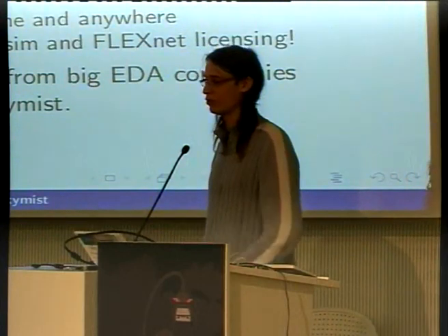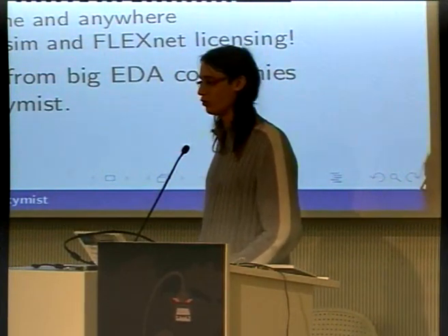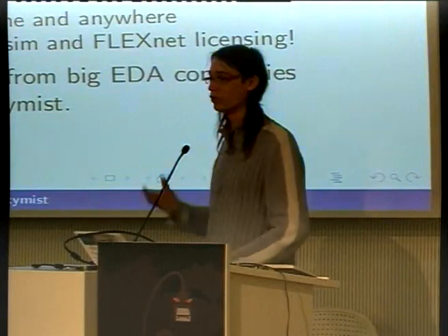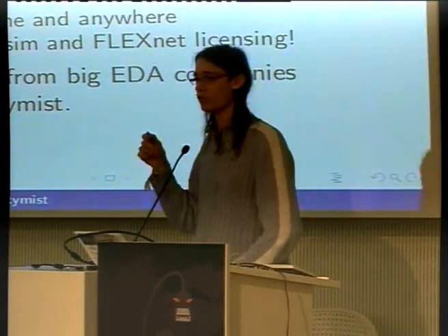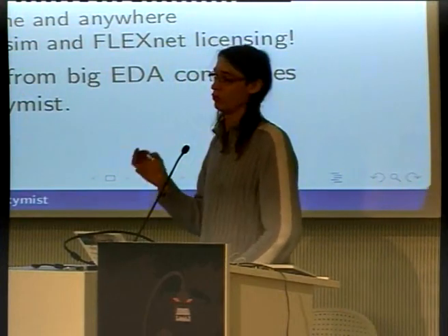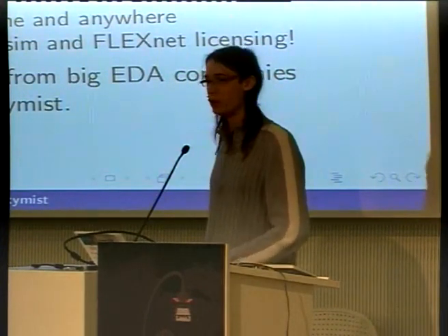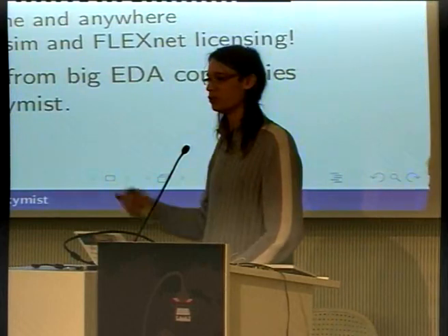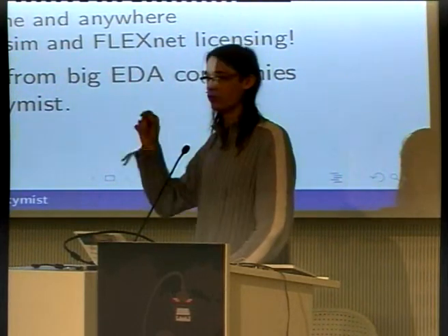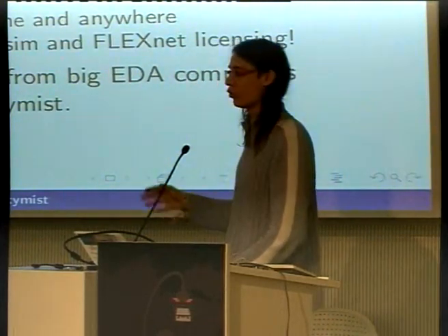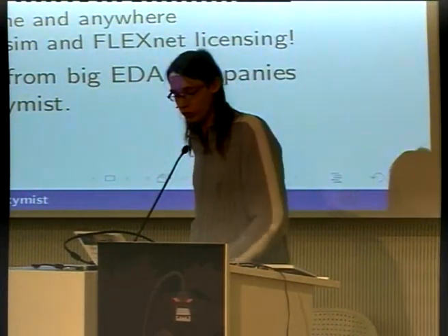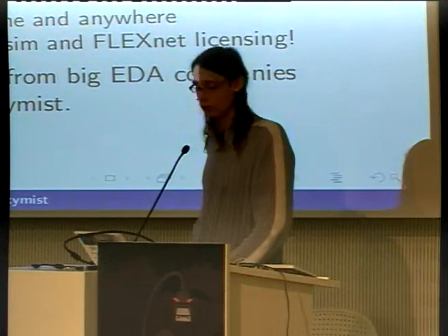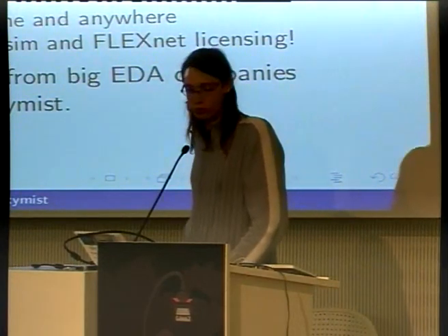You just cannot guess what's going on in the design if you don't have a simulator and if you're not able to peek inside your design. And even sometimes, with the most aggressive bugs, I post-process the result of the simulation to figure out where the bug is with some script, Perl, or anything. So the good news for you is that there are three simulators. There are Icarus Verilog, that I used a lot, GPL Cver, and there is also Verilator.